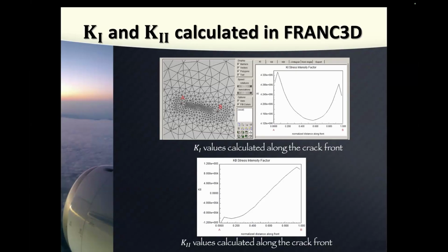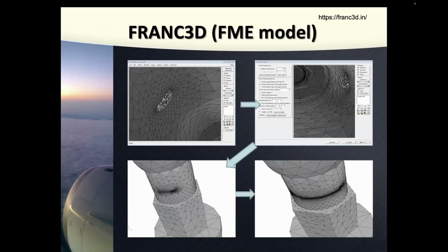But here in 3D analysis, we had the crack front, which means we have many nodes on the crack front. So it's like you can see on the previous slide, here I use a penny-shaped crack. And maybe it's not visible, but here you can see the generation of new crack fronts after calculation. And then this is how, again, step by step, we grew the crack and calculated the values for every step of growth.